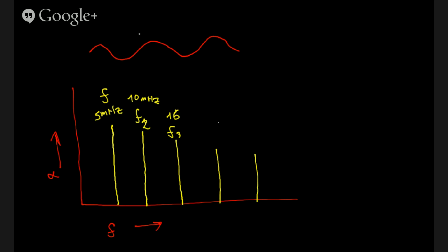Third harmonic, and on 20 megahertz, fourth harmonic, and so on and so forth. It would be slightly attenuated as the frequencies increases, but we do need to filter these out. Otherwise, operating on one frequency, you would always cause interference to each harmonic from there on.